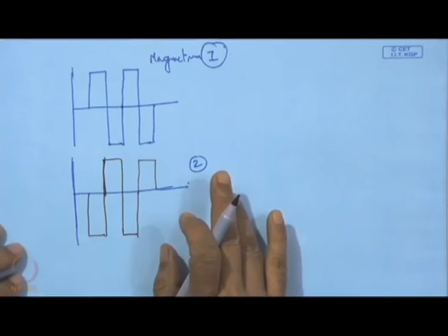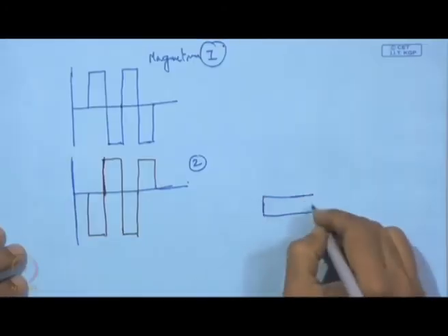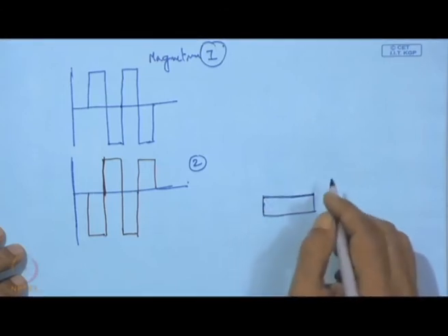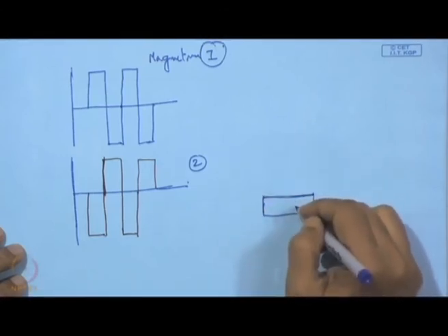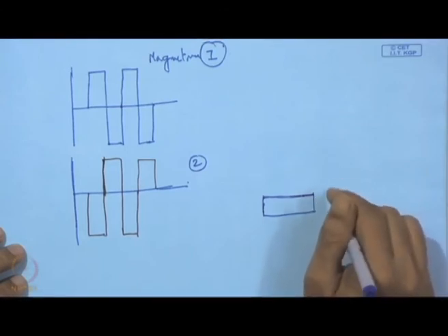In fact, in all these machines we can have the pulse generator for 2 targets, or we can have 4 targets. Even the substrate can also have this pulse generator supply, because of the simple reason that the substrate surface may be a conductor, but once a non-conducting film is deposited on the surface, then the DC supply will not work.